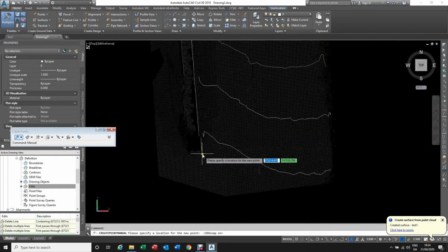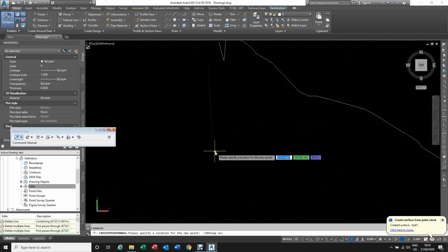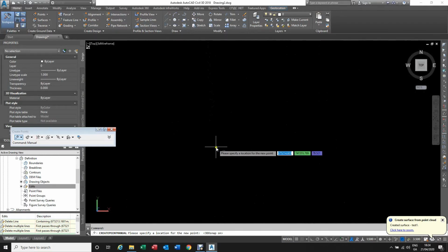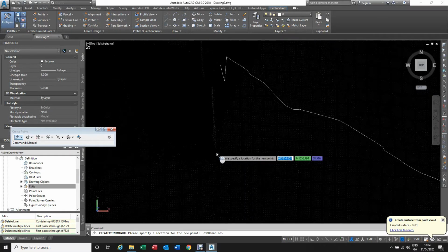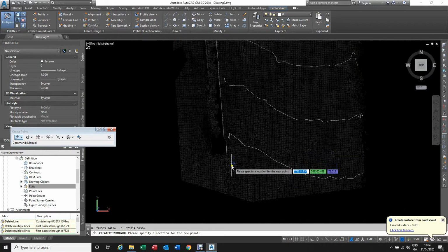It's actually, you can pick a point wherever you want on the scan point cloud. And let's say we want to give this one something like a wall. Enter point description, that's a WL. And because I had a snap-on on the point cloud, it get its elevation. So if you're happy with that elevation, just enter and you get that there.